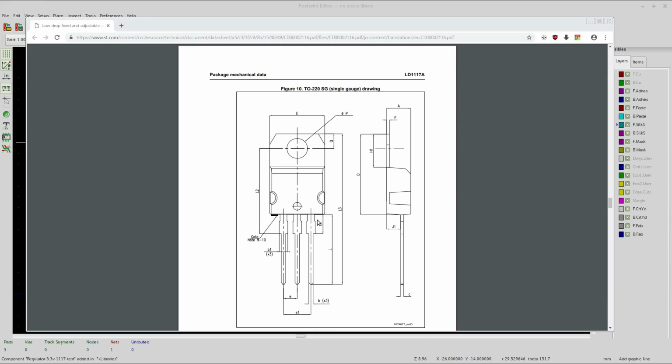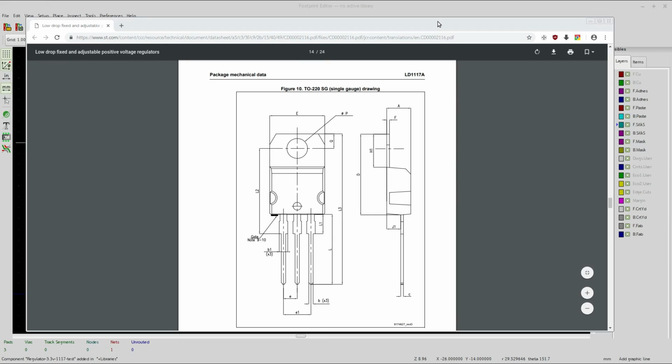So we'll come back to the mechanical drawing here to talk about this bend that's going to happen here, and beyond that, the placement of this hole, because as far as making things look pretty, we can lop the corners off here of our box and kind of make it look like the TO220 package, and maybe even draw a line here to say, hey, this is where the body of it is and this is where the tab goes.